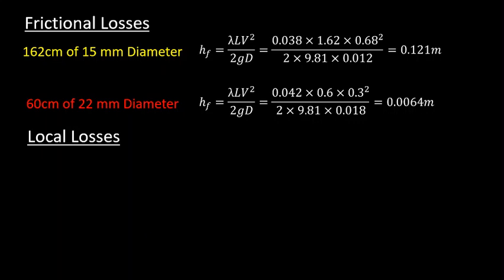This was to be expected as not only does it refer to less than half the total length, but as the head loss is inversely proportional to the diameter, whose increase in itself caused a reduction in the velocity, which was then squared in the numerator, this chain of connected variables shows how increasing the pipe's diameter can have a dramatic effect on the rate of head loss it incurs.